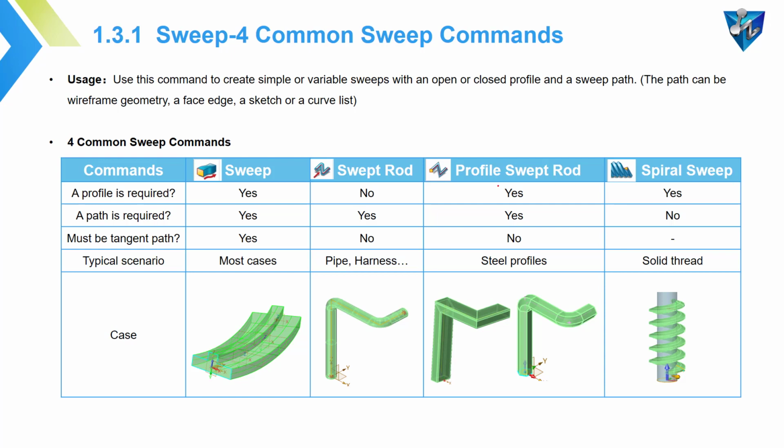Now let's see it one by one. For sweep, you can use it for most cases, and you need to define its profile and its path. And also, you need to notice that the path must be a tangent path.